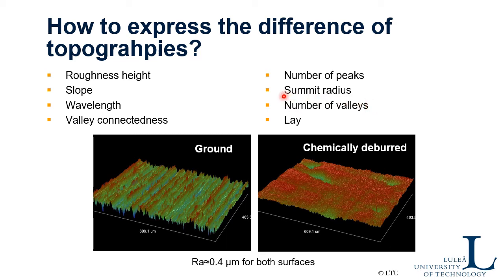It could be for seal surfaces, but could also be for gear surfaces maybe, and for combustion engine cylinder liner surfaces. The lay is the direction of the grinding marks here. So the lay is in this direction, we normally say. So the direction of the grinding is important many times.